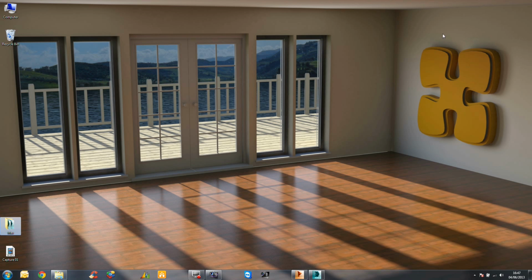We have some very nice soft shadows, not just in the corner, but around any detail as well, around the Man and Machine logo on the right hand side, and around the inside of the windows. For this render, I took the sky portals off of the door just to make the render a little bit quicker. That's why we don't have the shadows around the inside of the door.